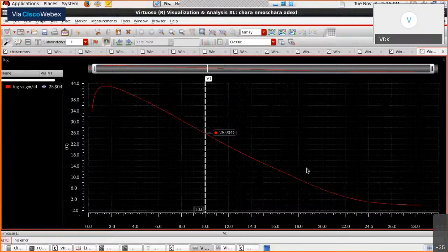So what all this means is that if I size W and connect this transistor in a common source amplifier with an ideal load resistance RL, and work this up, I should be able to get a maximum bandwidth of 26 gigahertz. That's what it gets.